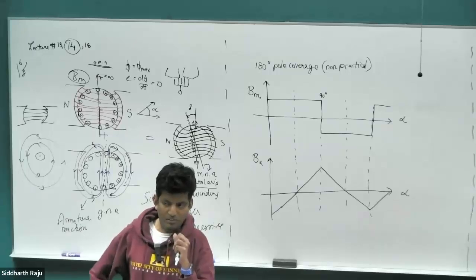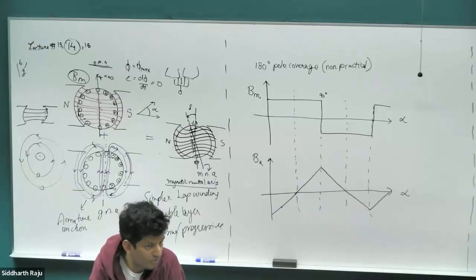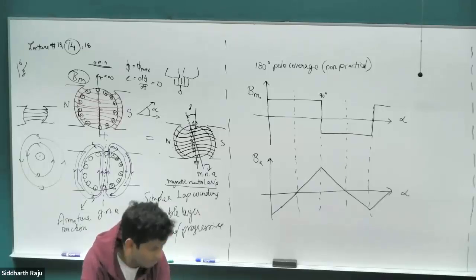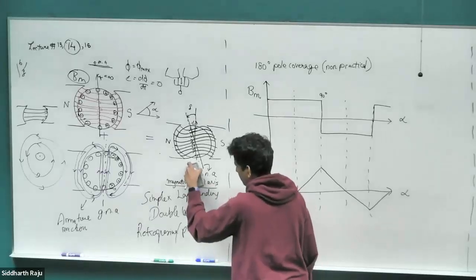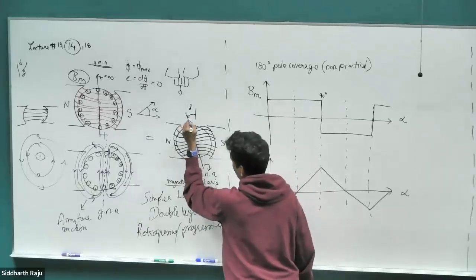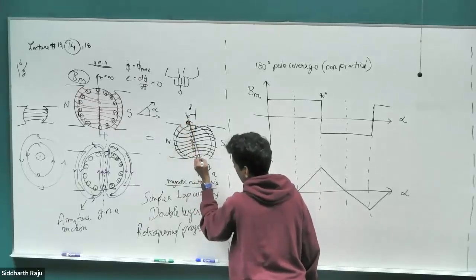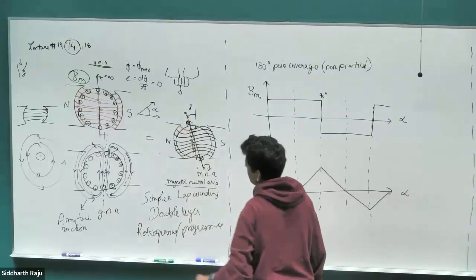There's a rather easy fix. Any ideas? Yeah, Thomas. Move the brushes. Move the brushes. Perfect. So we can shift the brushes, which is a very commonly used solution, especially for low current applications, small motors.